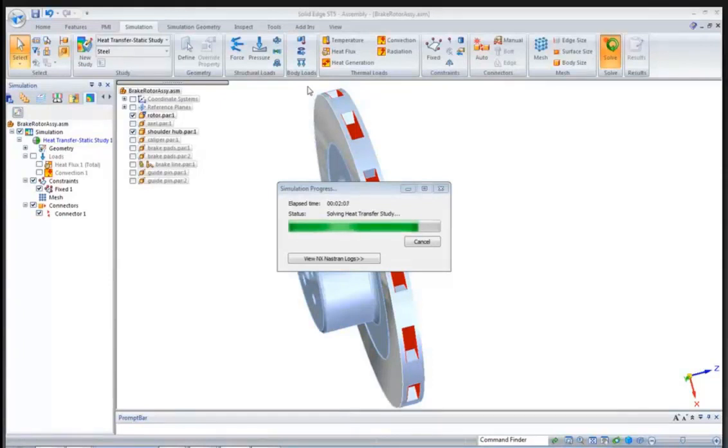So you've got 2 forms with convection. You've got the bulk fluid motion, which is called advection, and you also have the diffusion that we were talking about. So there's 2 forms of heat transfer with convection, 2 forms of energy transfer. So we can say with Newton's law of cooling that the temperature of this surface minus what they call T infinity, the temperature of the air way away from that surface, times a certain constant is equal to the heat flux. Well, that certain constant is called the convection coefficient.